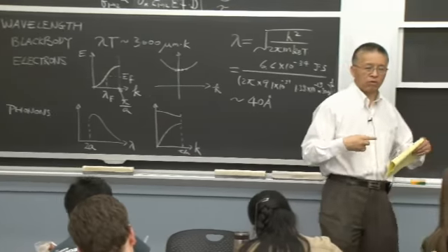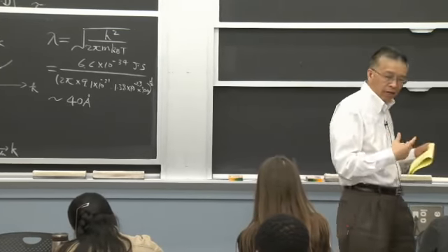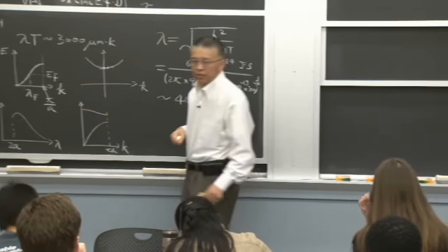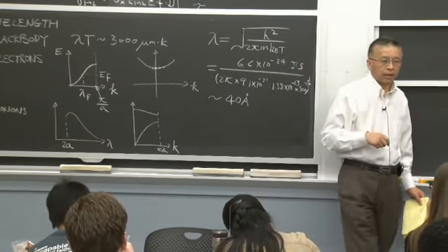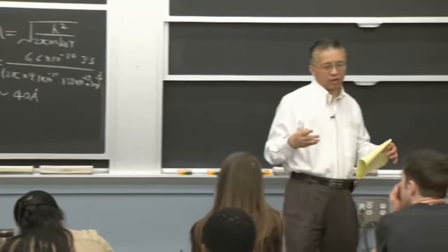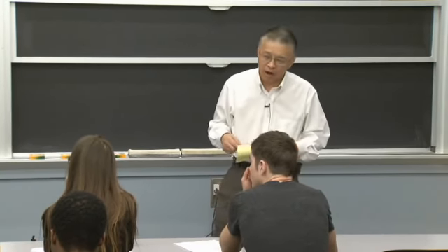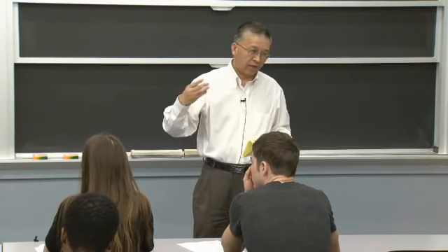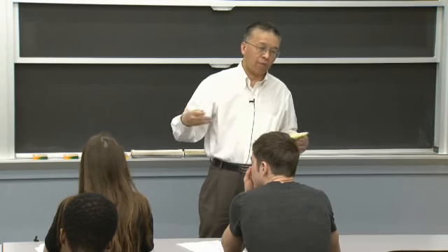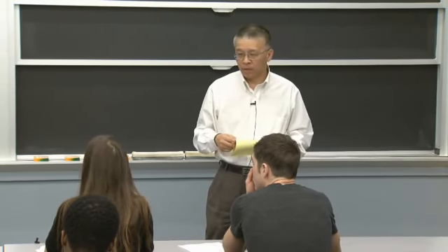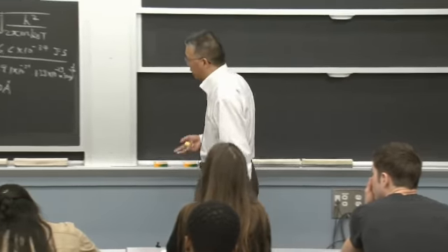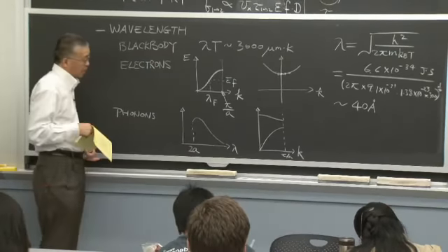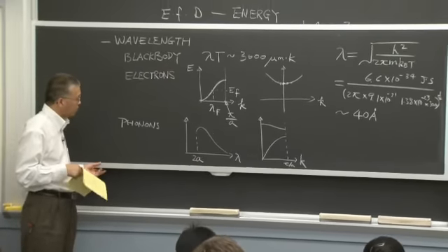So it gives you the average wavelength of those electrons with that energy kT near the bottom of the conduction band. This 40 angstrom seems awfully small, but we said before the sharp interface has zero thickness, and in fact you can deposit the layers almost atomically flat. So in those cases you should consider the wave reflection and transmission just as for optical waves.